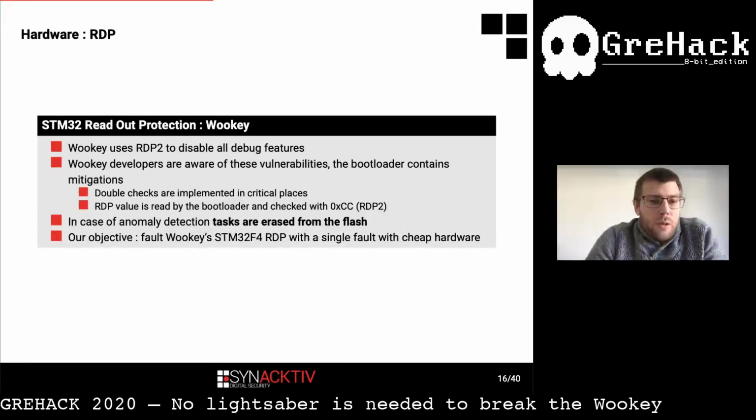So he used the RDP2 state on the production board, which means there is no debug possible. In source code review, we see that the developers are aware of these attacks, so they implement mitigation inside the bootloader. If the bootloader, for example, detects a wrong RDP value, then the flash memory is erased. So even if the attack succeeds, you cannot read encrypted secrets.